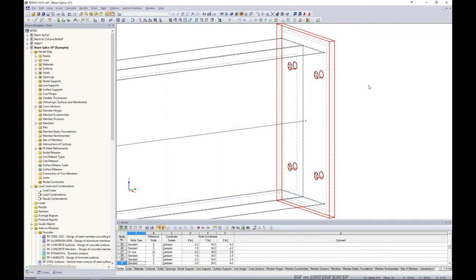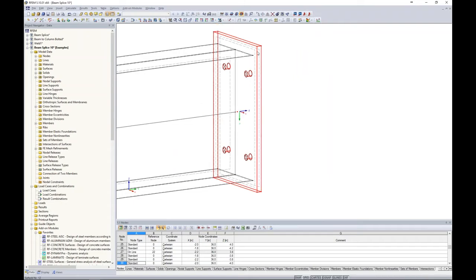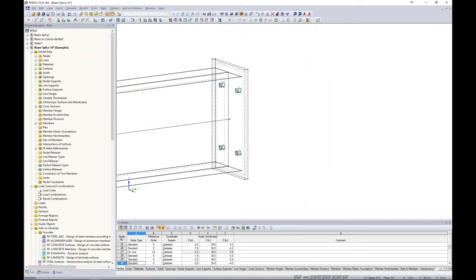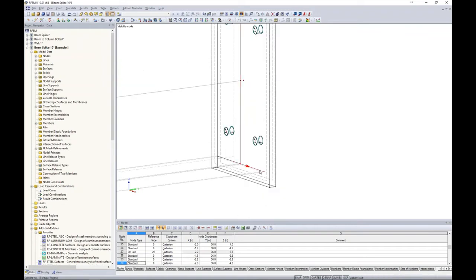Well, if we take a look back into the model, you'll notice that we have these line elements here, which are shown from framing our surface elements from our W shape. Maybe I want to take a look at here of just the plate elements, and we'll make a visibility here just based on these selected objects. So what I need to do is I actually need to copy these same exact elements to the back side of my surface.